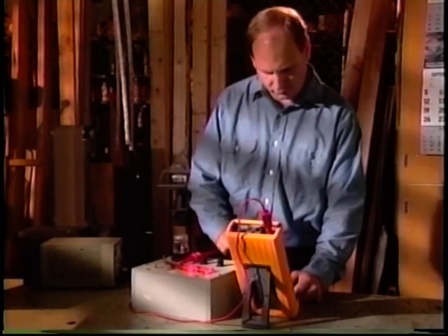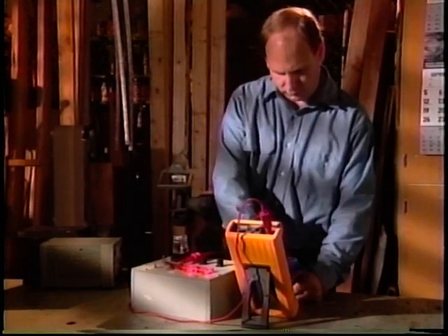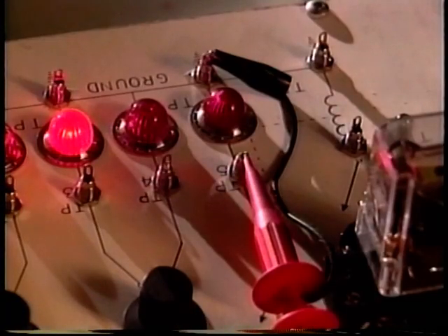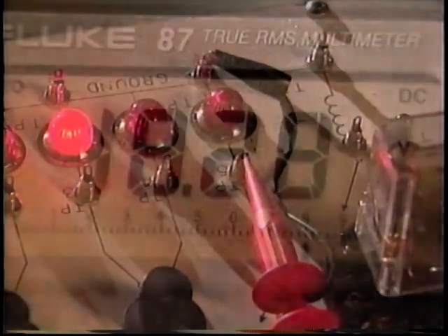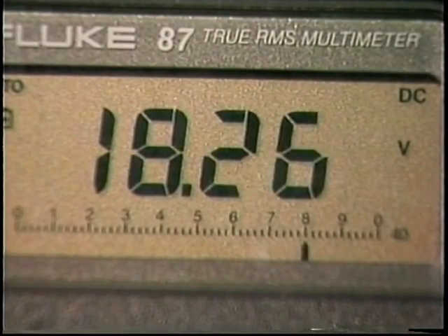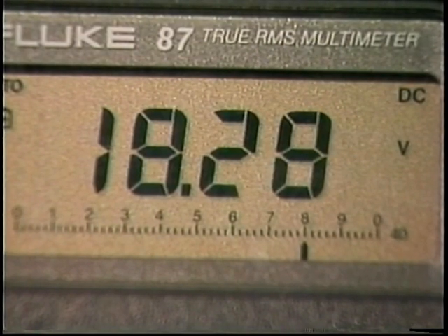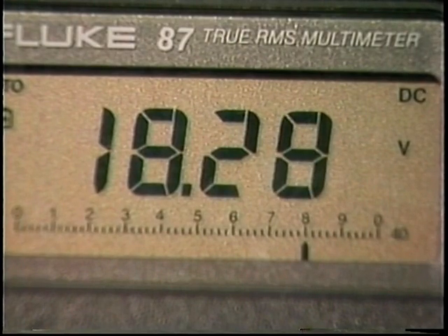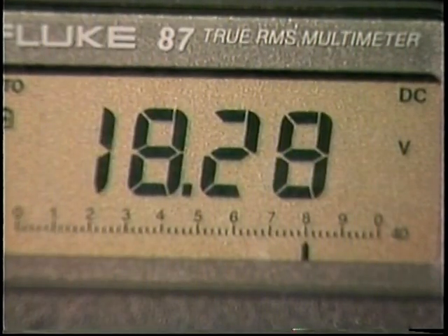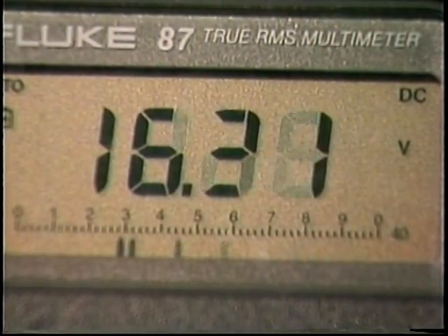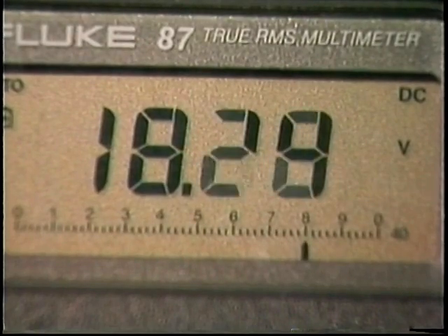For example, mechanical relay contacts may bounce open when exposed to vibration. Contact bounce causes intermittent problems in electrical equipment. The quick response of the bar graph allows easier detection of most contact bounce problems. Movement of one or more segments the moment the contact opens indicates contact bounce.